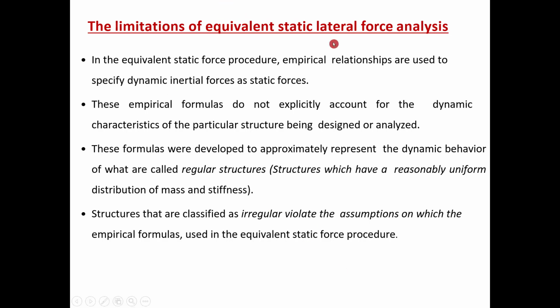So the limitations of equivalent static lateral force analysis is the empirical relationships are used to specify dynamic inertial forces as static forces. So this conversion is there to dynamic to equivalent static forces, and these empirical formulas do not explicitly account for the dynamic characteristics of the particular structure. That means that mode shapes and the building frequencies are not directly taken for the equivalent static lateral force method, which will definitely induce some errors.